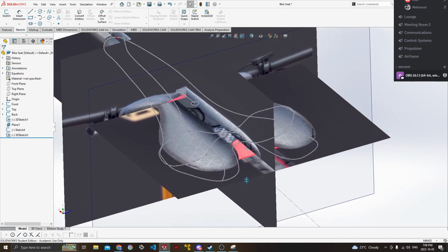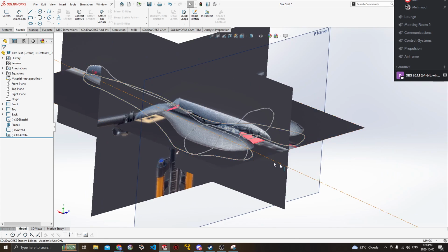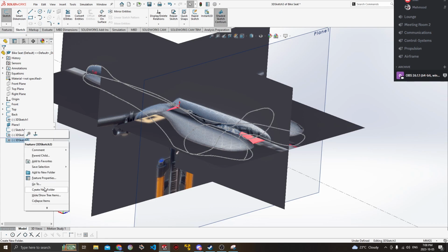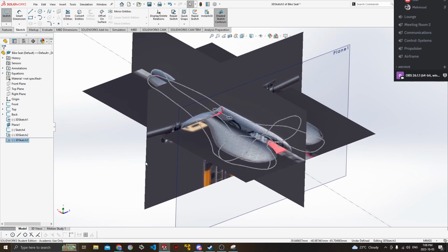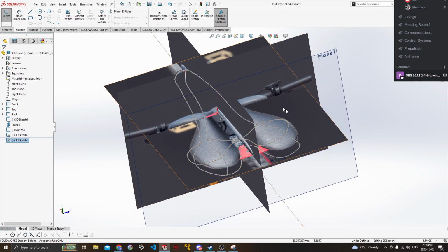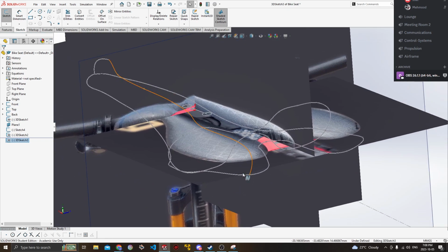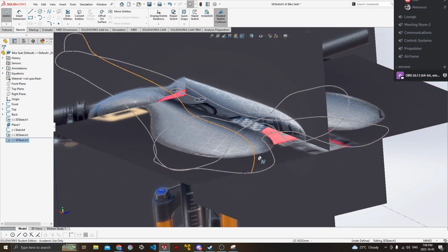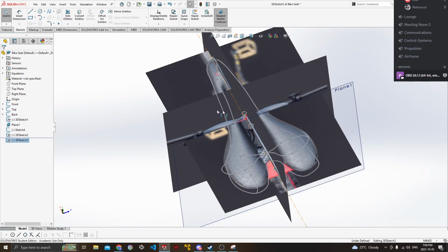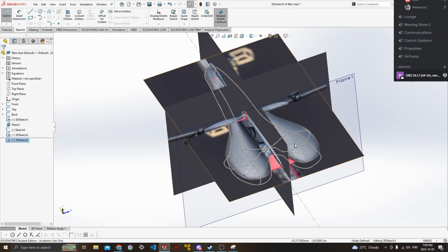Okay, so what we're going to do is another 3D sketch. And we're just going to rename this one to, I guess you can't rename it until we've started, that's fine. But what we're going to do is use the Convert Entities tool. So all of these splines that we've created now are all reference geometry. These are not going to be used for the actual surfaces that we create. The reason why we do that is because it can be very difficult for us to rebuild these and get them exactly the same. So what we want is wherever there's going to be separating geometry for surfaces.